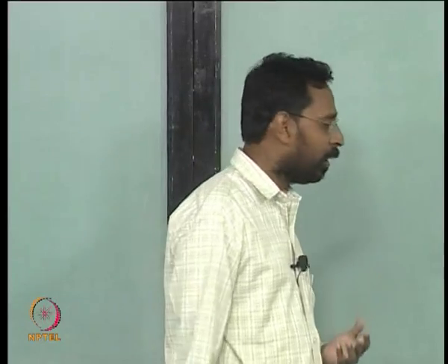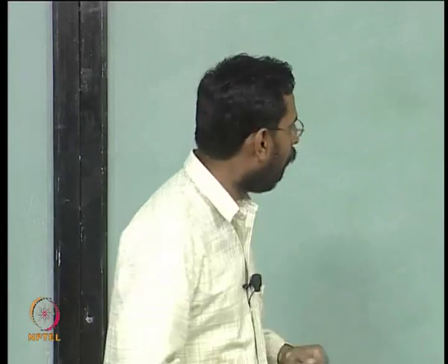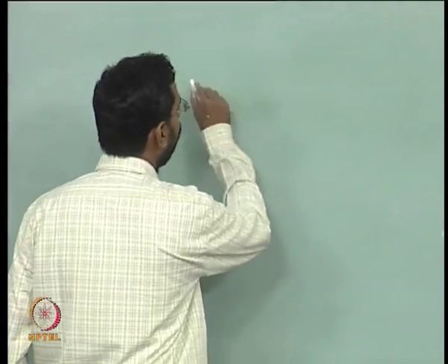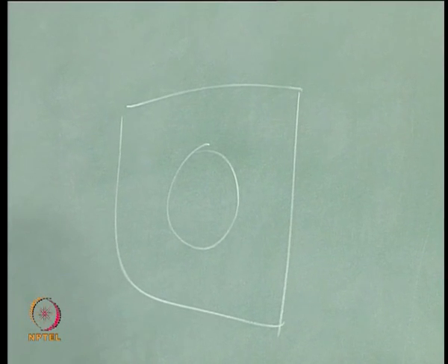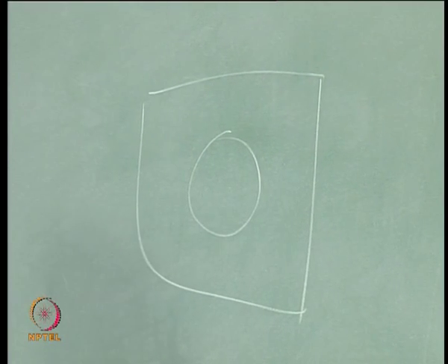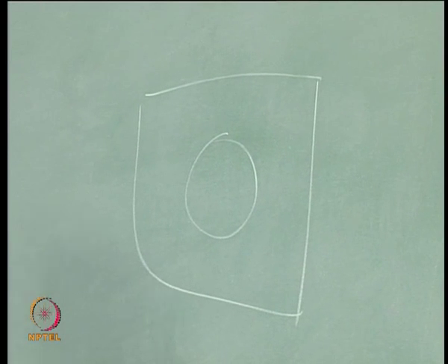I was telling you that each plane in a crystal, because when I say a solid, I am not talking of a glass here, I am talking of a crystalline solid that is coming out of a liquid, and if it is a crystalline solid coming out of a liquid, it has unit cells, it has planes, and different planes have different surface energies. If different planes have different surface energies, how do I assume that a liquid will have a spherical particle? Because the moment I say spherical, what kind of a crystal structure can I imagine which would give me a spherical particle?